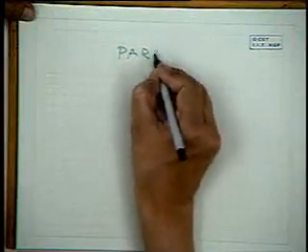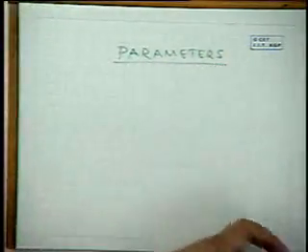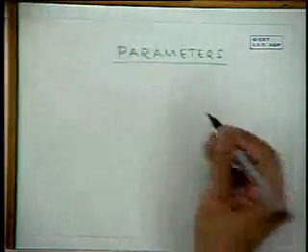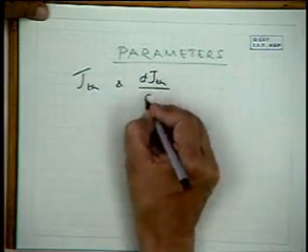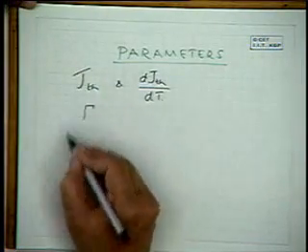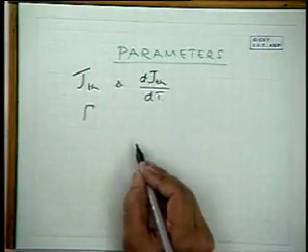So since we are talking about device properties, let me just mention some of the important parameters for a laser. We have already discussed some of these. One is, of course, threshold current and dJTH/dT. Then the confinement factor gamma. For each structure we have to find out the confinement factor, because this determines JTH and dJTH.